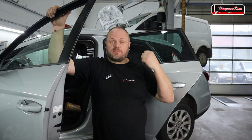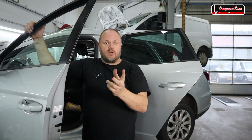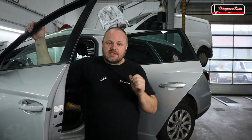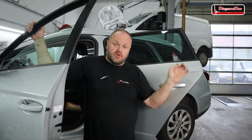We've just confirmed we've got powers and grounds at the module in the back. Now that module is also new, so it should be able to communicate. You never know, but it should be. Now, we also know that the powers and grounds at the module in the front are okay. How do we know? We could read fault code, so it's communicating, so it's happy. So in the next step, let's take a closer look at the communication between the module in the front and the module in the rear.